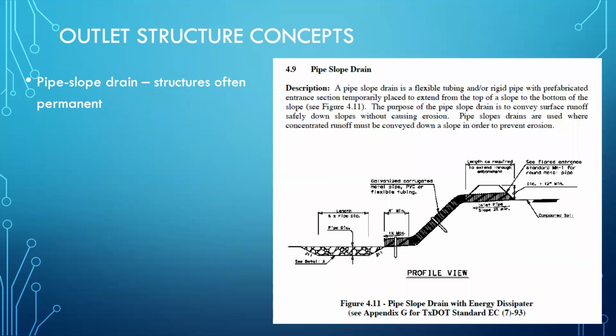So that's one way. Another technique is, I kind of like this one because it's actually fairly ingenious. If we have a flow up here, we have a berm protecting it, and we need to convey it down to a substantially lower elevation, we can use a fairly large diameter pipe and run it down the side of the berm. Slope doesn't matter. Have a fairly sharp change in slope near the end of the pipe, not at the end of the pipe.